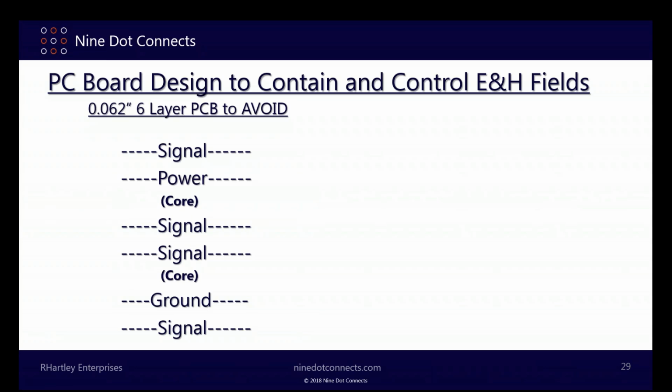From a signal integrity standpoint, again, this won't create enough of a problem to cause an issue. If all you care about is signal integrity, hey, knock yourself out. This board will be just fine. But if you care about EMI, or if you're doing analog design where you care about even a small amount of interference, this is a very bad board stackup.